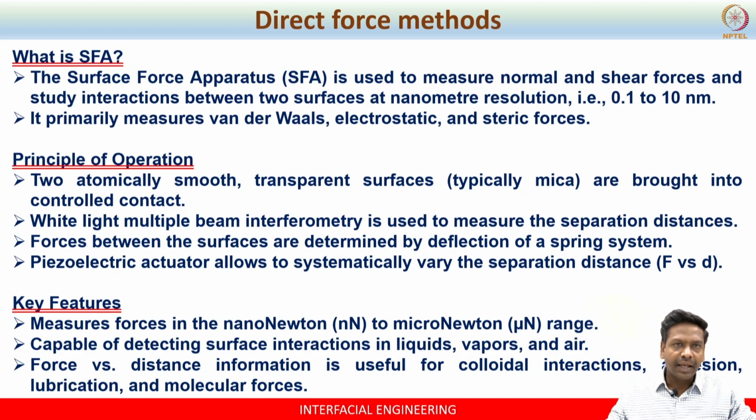Okay, so this actually measures normal and shear forces, right, as a result of the interaction between two surfaces, at nanometer resolution, usually in the range between 0.1 to 10 nanometer, a few tens of nanometer separation distance. So by measuring these forces, one can actually obtain the information between force and separation distance. The principle of operation is very simple.